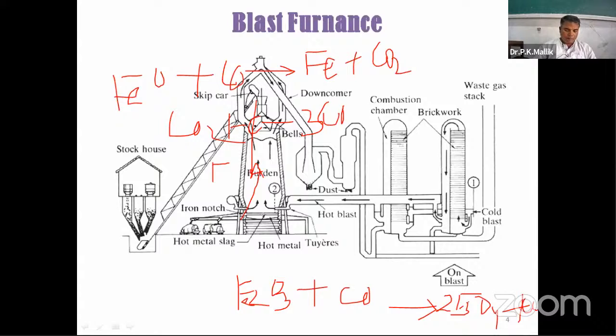Although the purpose of coke is obviously to act as a reductant, it also plays another critical role in that it behaves as a supporting pillar for the overlying burden. In the region below the cohesive zone, otherwise known as the sticky zone, everything else is in molten conditions.